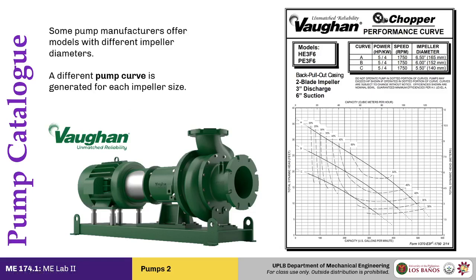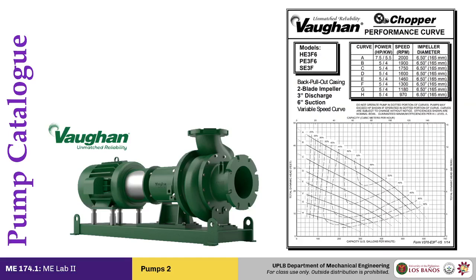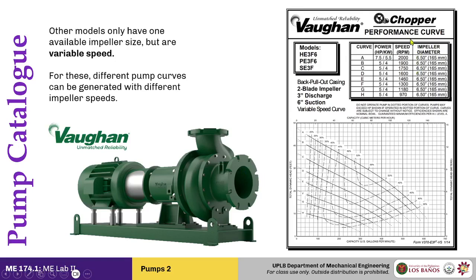So for pumps of a particular size, especially motor-driven pumps, the motors, if they consume AC, usually only operate on one speed. However, you do see variable speed motors, and when you do, instead of differing impeller sizes, you have differing impeller speeds specified. So if you see here in the column, you have a particular speed defined, and they tested the pump performance along that particular speed.